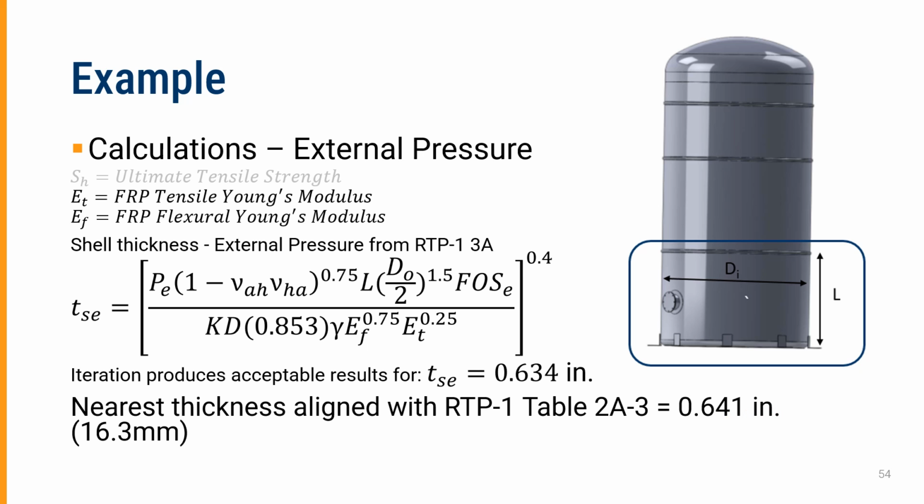From that, we're able to know what the design is. Now, in fact, this equipment was built almost exactly to that thickness. 16.3 millimeters. We normally are seeing this vessel to be 16.5 to 18 millimeters. Remember I said there's some variation in thickness when they make things, because we have a relatively random process, or more randomness in the process, making it with involvement by people with paint rollers.